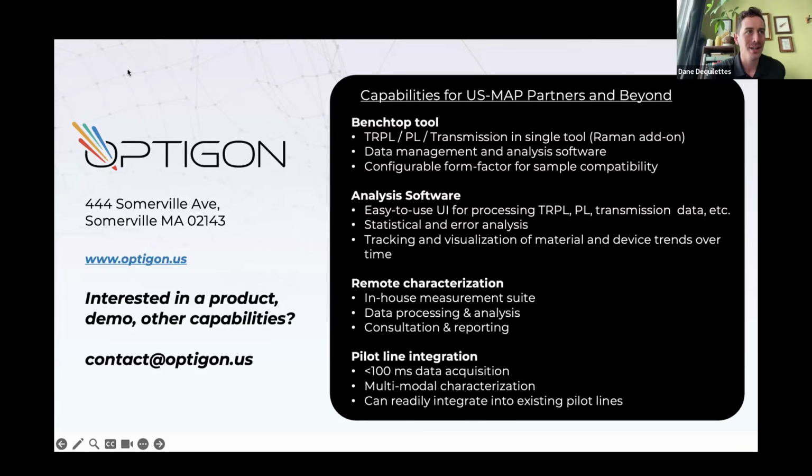Yeah, definitely. For the work that we're doing with your team, a lot of it has to do with just looking at the half stack. So we're not taking into consideration too much of the non-radiative recombination that happens when you introduce that next layer. Especially in the open circuit voltage, we overestimate because we assume there's no additional non-radiative recombination when you add that layer.